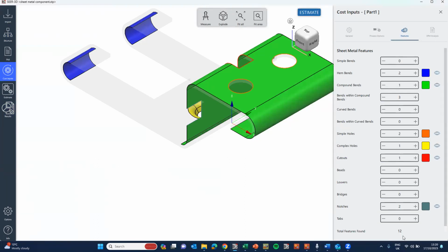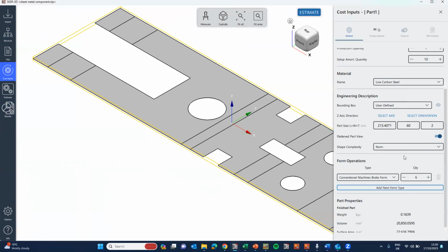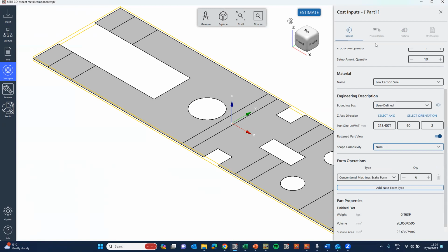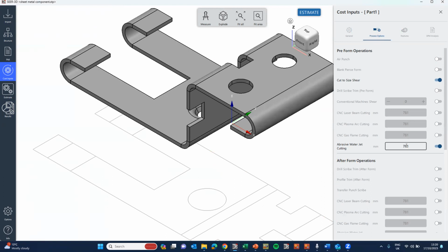And each one of these has a ranking and a scale. And based upon that, in the environment, it sets up this ranking scale. You can change it, but this is what it recommends based upon the INI file. Secondly, it's going to come along, we're going to do some abrasive water jet cutting. We don't have to. We can say we want to do laser beam cutting instead, and we can swap that over. But the idea is that you set your environments up for a given process, so that the skilled man can set this up with all of his knowledge and experience, and the less skilled operator, maybe somebody who's not had as much production time, manufacturing time, can come along and with confidence use the correct environment and get himself a good cost, or herself a good cost accordingly.